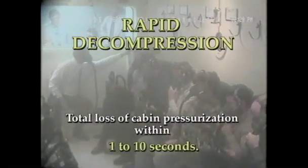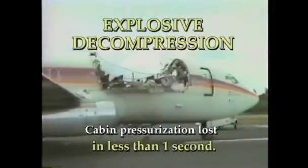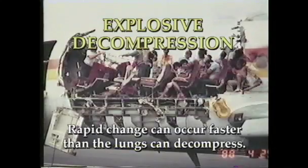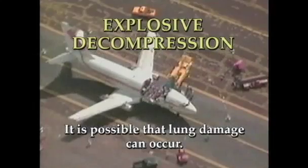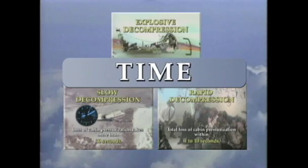Rapid decompression, when there is a total loss of cabin pressurization within 1 to 10 seconds. Explosive decompression, when cabin pressurization is lost in less than 1 second. This rapid change can occur faster than the lungs can decompress. Therefore, it is possible that lung damage can occur. Please note that the main differences among each of these types of decompressions is time.